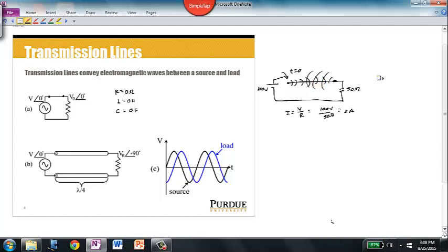To analyze such circuits, we will typically start with a circuit model that we call a transmission line, which is really just a wire that we develop to have a realistic circuit model. By developing the circuit model, we're going to begin to analyze why delay occurs in wires, and we will use transmission line models whenever the length of wire connecting a source to a load is a significant fraction of the signal's wavelength. And so down here I show some of the ramifications of actually using a transmission line.